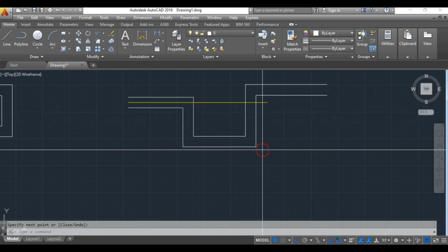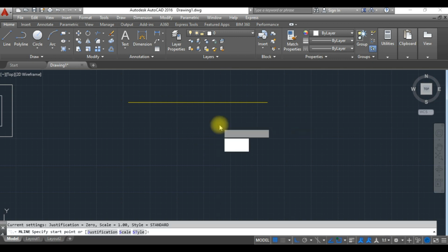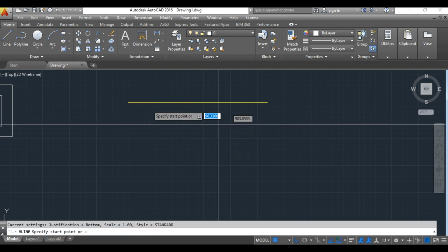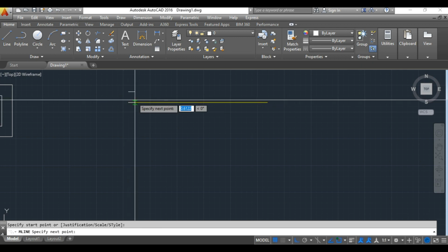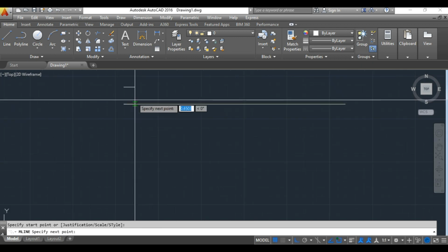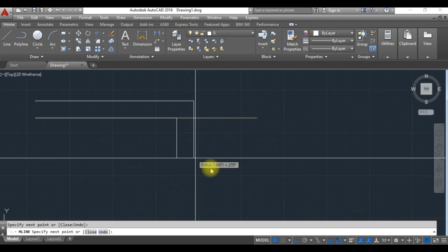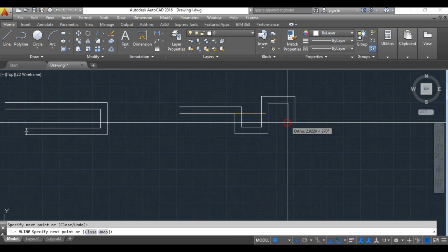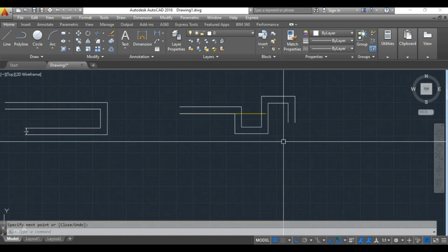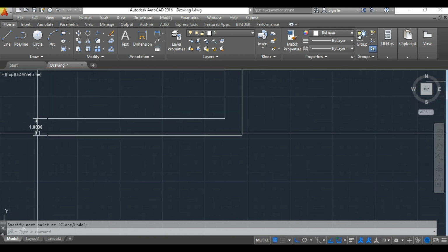The same way, if you want to plot with respect to the bottom line, I will go with bottom. So here, if I consider this reference line as my bottom, the rest of the multi-line will be plotted on the upper side. You can check here, it is plotting on the upper side. Right? This is about your multi-line command, and the spacing you are getting between these 2 lines will be 1 unit.